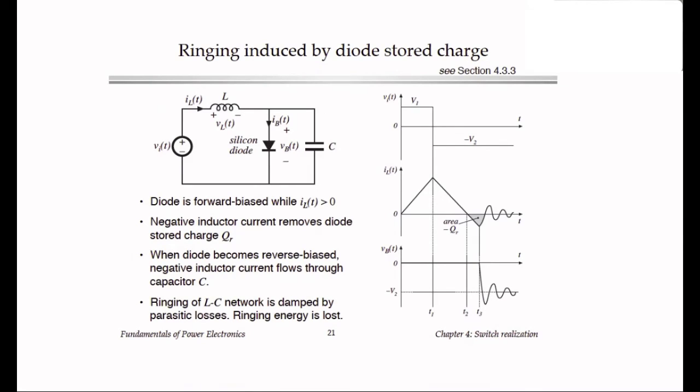And lastly, we've discussed the diode reverse recovery. It actually induces some switching loss in the MOSFET in, let's say, a buck converter. Sometimes we have circuits where the diode is not directly connected to a transistor, and here's an example of one. This often happens in transformer isolated converters, or in some other converter circuits that have effectively an inductor that provides current to the diode.